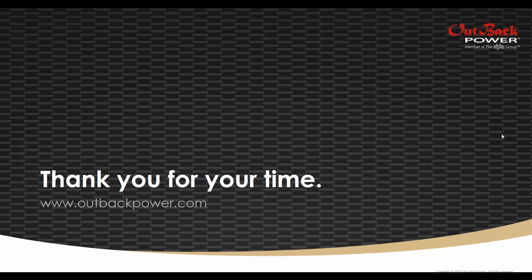Paul asked if SkyBox could be considered an uninterruptible power supply for the whole house, assuming correct sizing, etc. So for example, would it transfer from grid to battery and not have to reset electronics and computers? So Paul, I wouldn't call it an uninterruptible power supply, but in general, the transfer time is around 20 milliseconds. So we're not seeing the need to reset electronics, or reset the router or change the clocks on the microwave or on the oven.